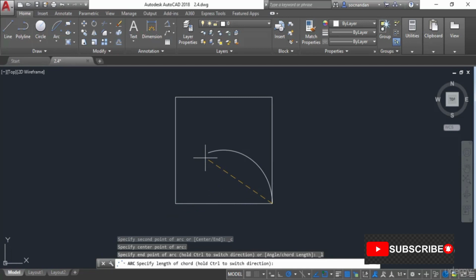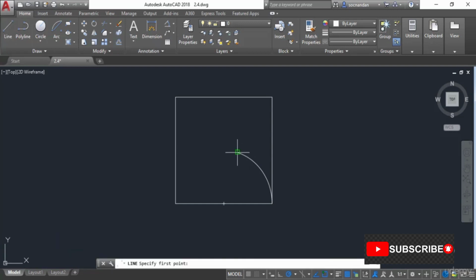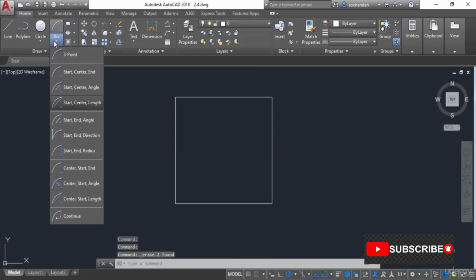So let's say that we want to make an arc with a chord length of 60 units. So let's type 60 and press enter. Now in this case, the length of the line joining this end point of the arc and this end point of the arc should be equal to 60 units. So that is the chord, and this is the chord length here, and the length of this chord is 60 units. So let's erase it, and let's look at other options.